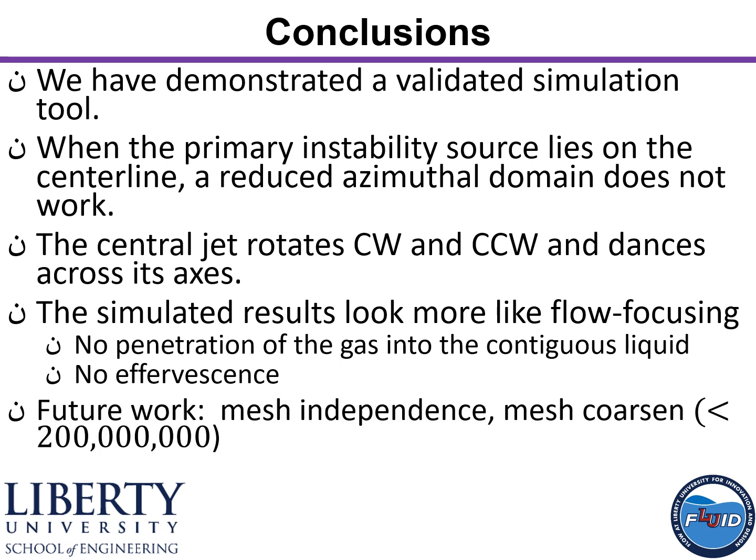For future work, we need to continue our mesh independence study. I'm running an M3 now, but also more importantly, I want to coarsen the mesh downstream of where the VOF is completely converted to DPM, so that we can get to less than 200 million cells, which is where we are in M2, or M3, excuse me.